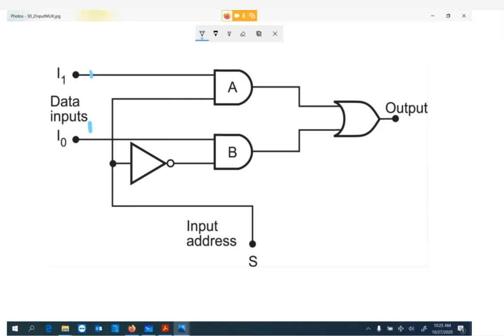So right now, if we have a 0 here, it means we have a 0 here and a 0 here. By having a 0 here, that means this is a 1. And of course, if there's a 0 here, nothing outputs. And if there's a 0 here, nothing outputs. But if a 1 comes along from our data in, we get an output.